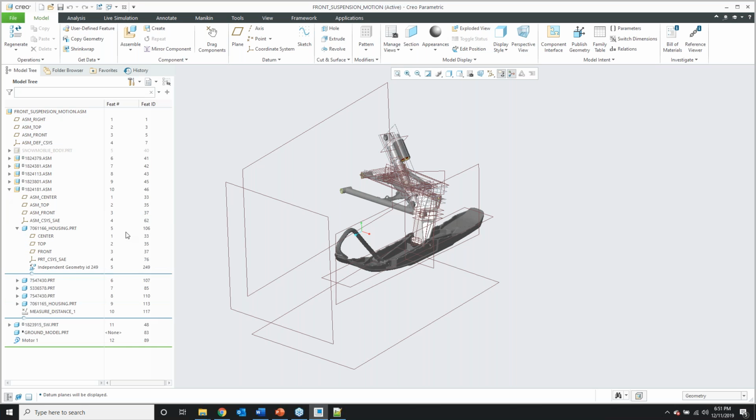So if you ever worked with circular references or tried to fix them before, you know this is vital, because the circular reference file will tell you what feature and what ID is referenced to other features and IDs. Okay, so that's good. And you can go in here and you can add as many columns as you like.